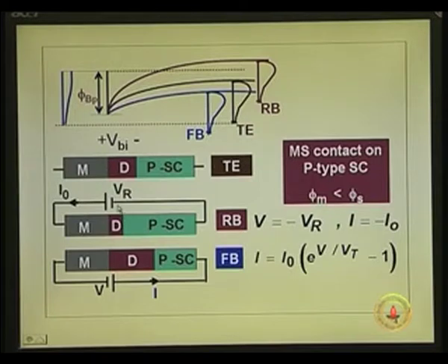So, now here this polarity of this voltage, if it is the same thing, the band bending there will increase, it will push the energy band diagram valence band upward. So, that is the reverse bias situation, that is whatever built-in potential was there, you add up this quantity, that is extra voltage that you are adding up, okay. That extra voltage added up is Vr, and you get reverse bias.